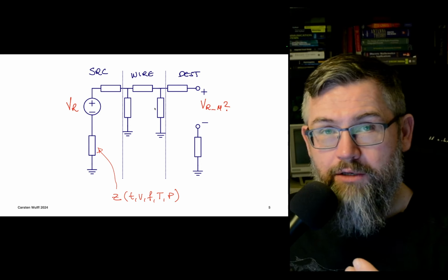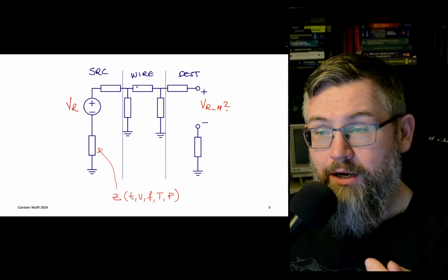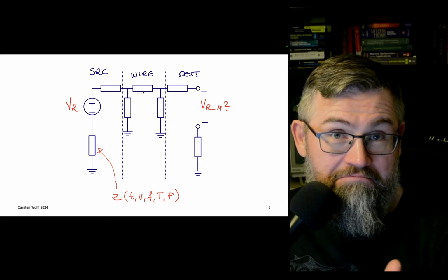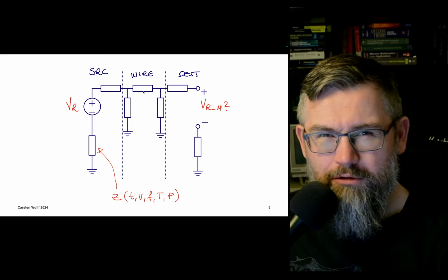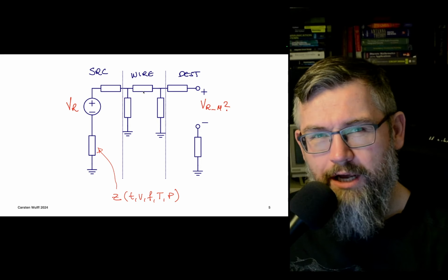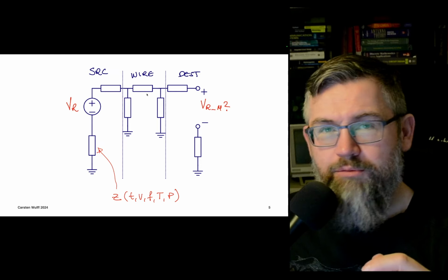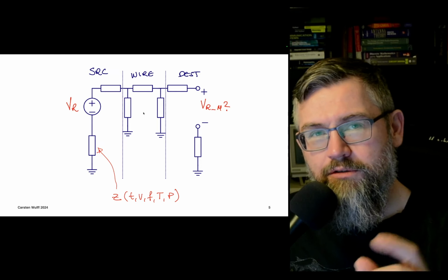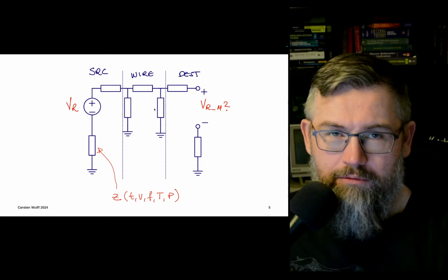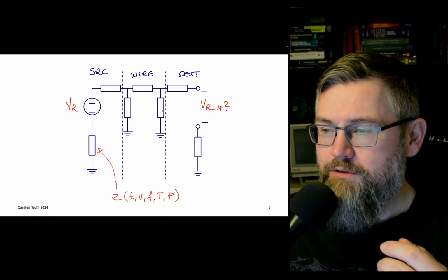By the way, a good way to model a wire is two capacitors to ground and resistance between. That's a common model used for digital circuits, wire delay. You have two capacitors to ground, and there's a resistor in between. And you split the capacitance of the wire into two, and that kind of works for simple models.